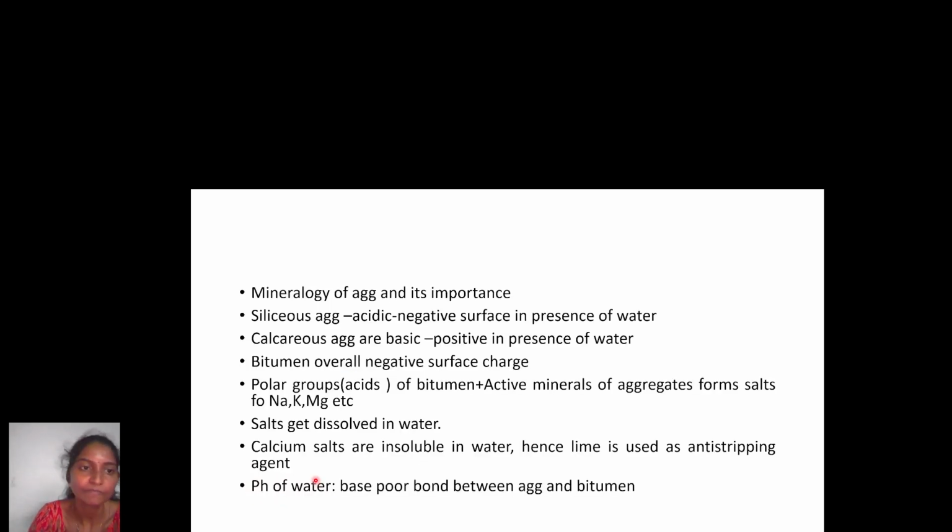Corresponding to this, usually we also will see one problem that is being solved in the upcoming slides. So NMAS is a sieve size. This is just one sieve size larger than the 10% retained sieve size, and maximum aggregate size is one sieve size larger than the NMAS.